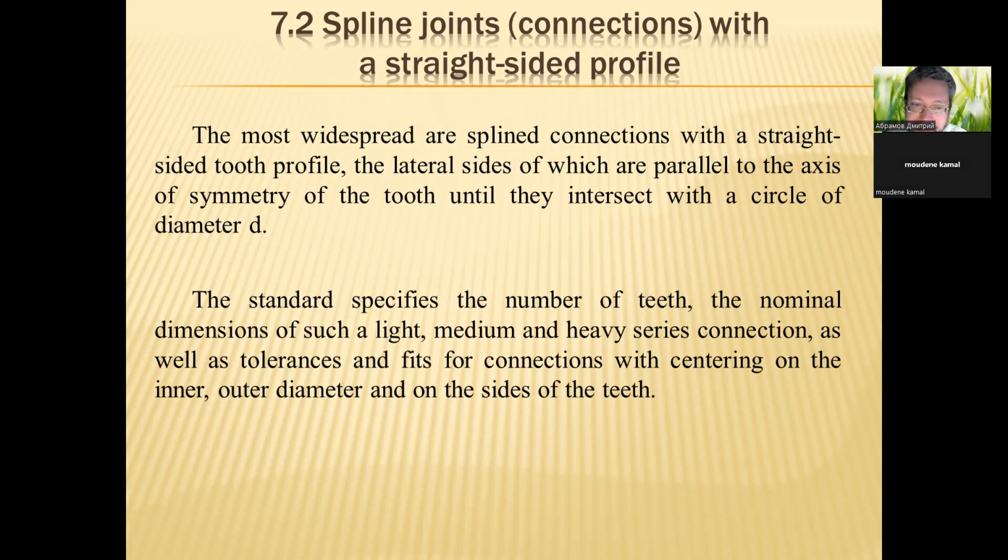The standard specifies the number of teeth, the nominal dimensions of such light, medium, and heavy series connections, as well as tolerances and fits for connections with centering on the inner, outer diameter and on the sides of the teeth.